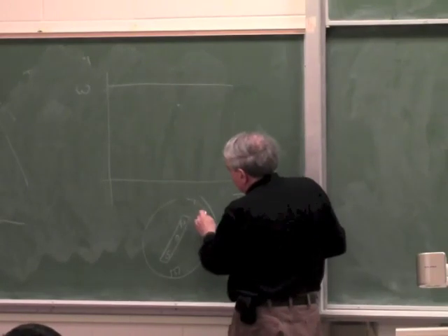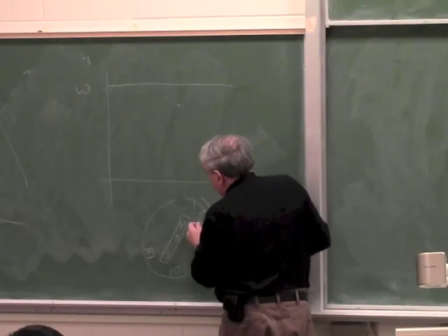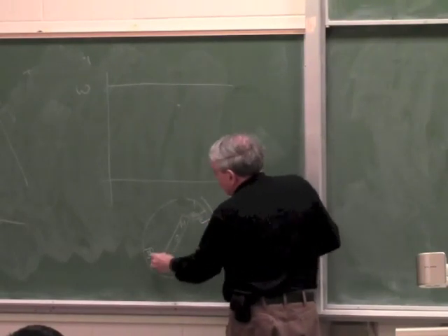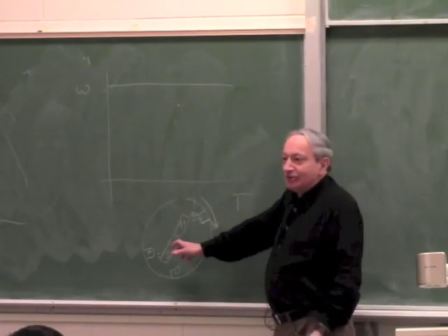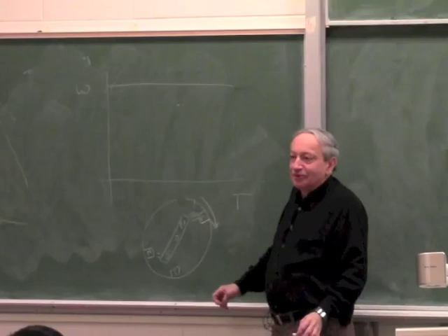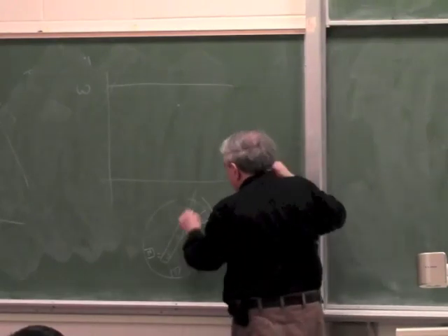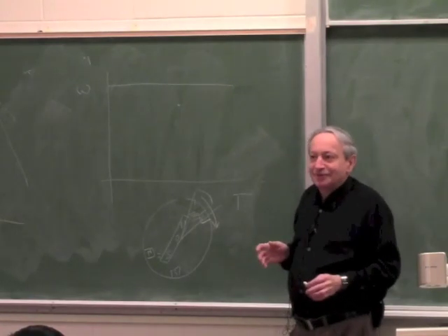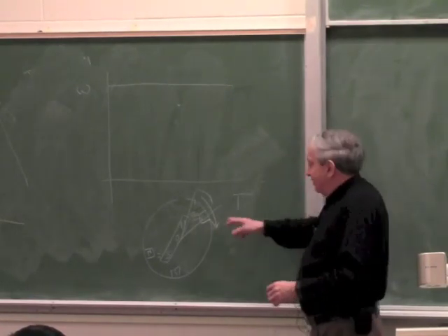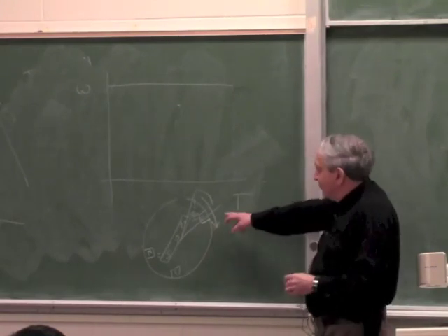So if you have a bigger torque, the poles are like this, NS, and this is a magnetic attraction, but at some point, if you put more and more torque, it just breaks lock, and once it breaks lock, it loses all torque. Does somebody remember what this angle is called? It's only a week ago. Power angle, yeah. Sometimes it's called torque angle in some textbooks, but it's usually referred to as power angle.